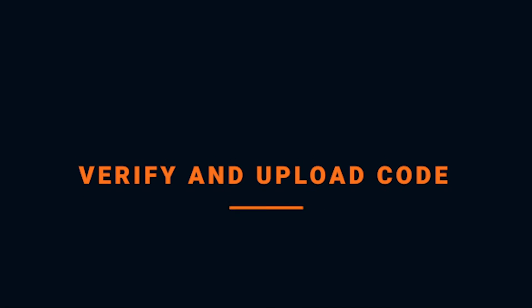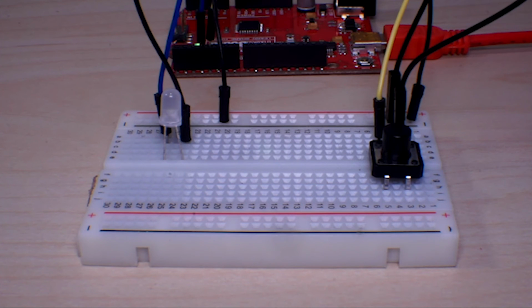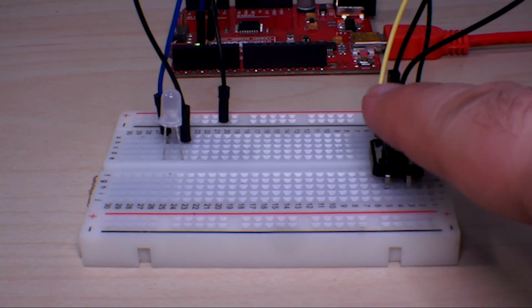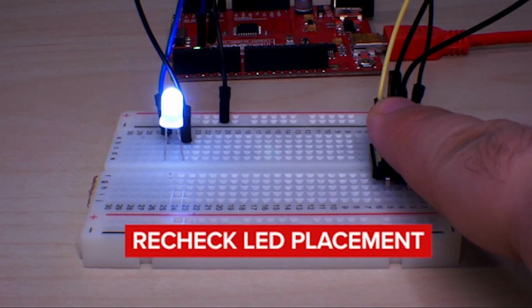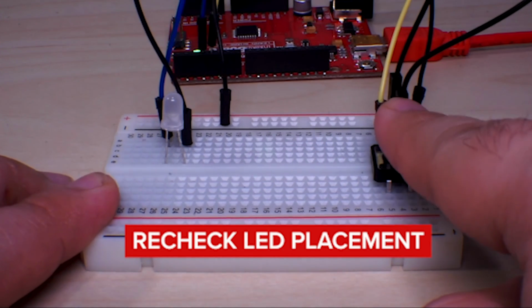After uploading your code to the Redboard, confirm that your push button is functioning correctly by pressing down and turning on your LED. If not, don't worry. Recheck your wiring to make sure they're aligned with the legs of your push button. Also check the placement of your LED. Make sure the short leg of your LED is connected to the ground and the longer leg is connected to pin 3 on the Redboard.